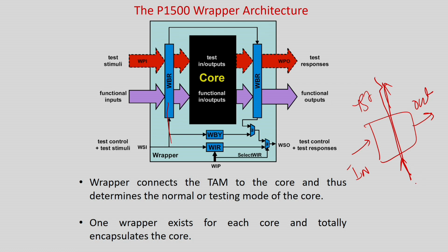If I put another register over, this is another input to the core, another input line. So this is your scanning. Maybe I have to give a value of 1, 0 as the inputs to the core for testing. As in a scan mode, this one will be disabled, and this one will be disabled, in test mode. So I apply a 1, apply a 0 as a boundary mode, and it will come and apply to the core.